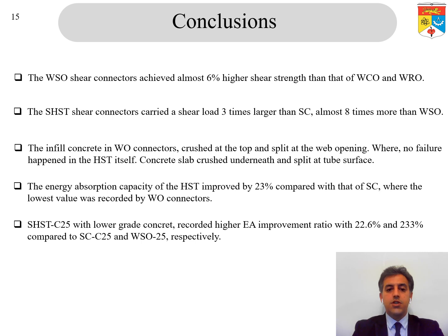The hollow steel tube shear connectors carried a shear load 3 times larger than the shear stud and 8 times more than the web square opening. The infill concrete in the web opening crushed at the top and split at the web opening, where no failure on the hollow steel tube connector was recorded. Energy absorption capacity of the hollow steel tube connectors improved by 23% compared with the shear stud connector as a reference connector, where the lowest value was recorded by web opening connectors.